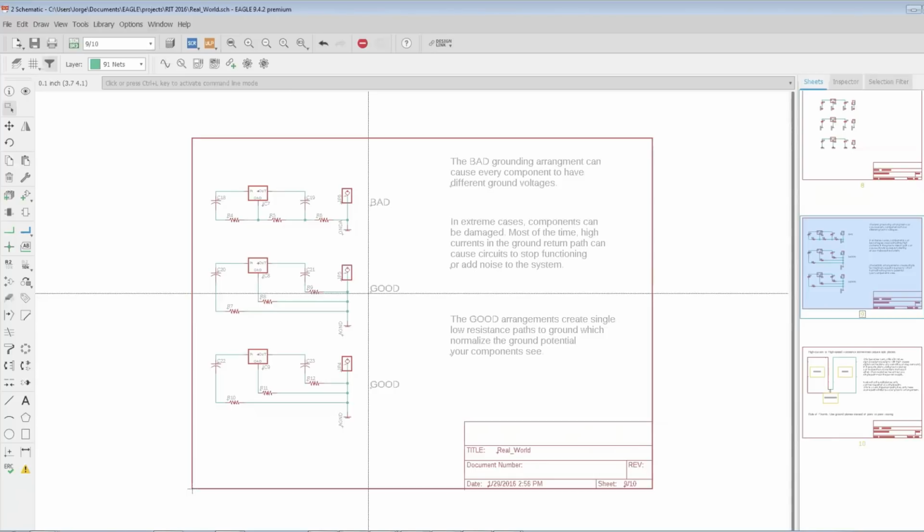Very simple. Okay, for your signal integrity to be preserved, for your signal not to distort, it needs to see a constant impedance as it travels through your board. Okay, and those impedances should be matched to minimize distortion. Finally, the last concept that we've covered is ground.